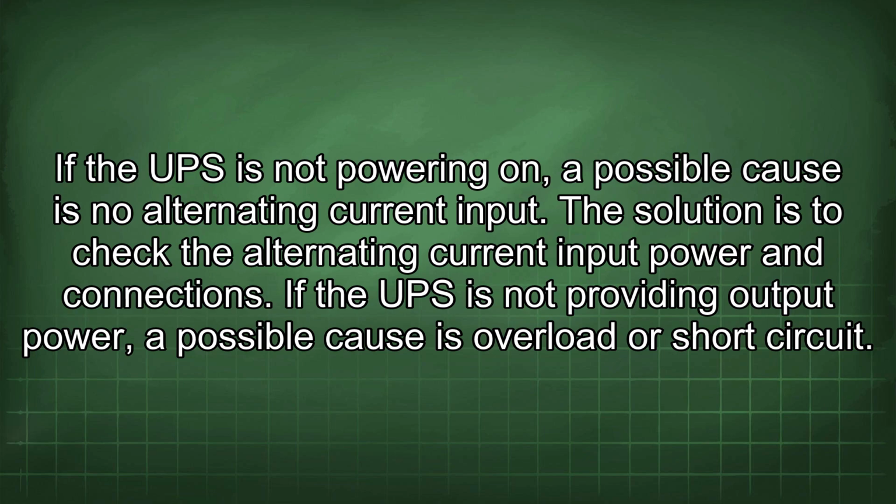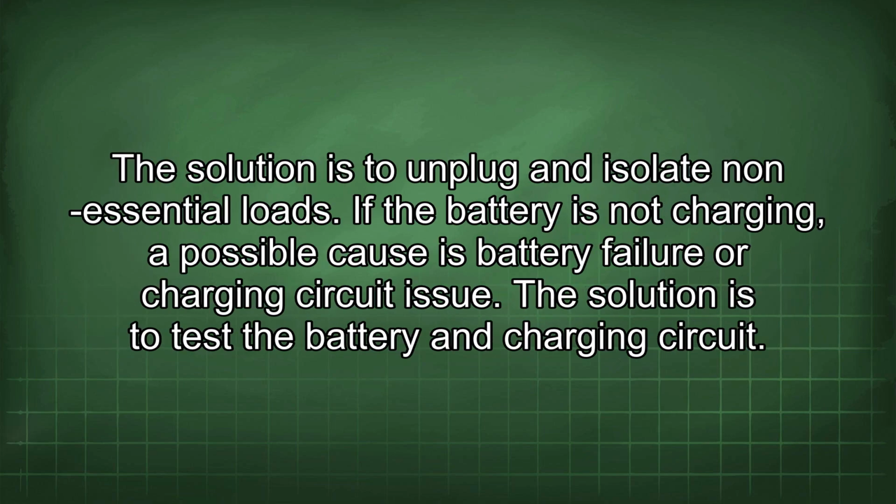The solution is to check the alternating current input power and connections. If the UPS is not providing output power, a possible cause is overload or short circuit. The solution is to unplug and isolate non-essential loads. If the battery is not charging, a possible cause is battery failure or charging circuit issue. The solution is to test the battery and charging circuit.